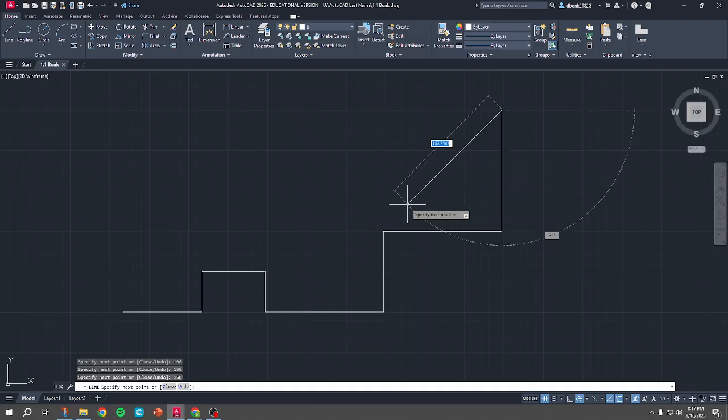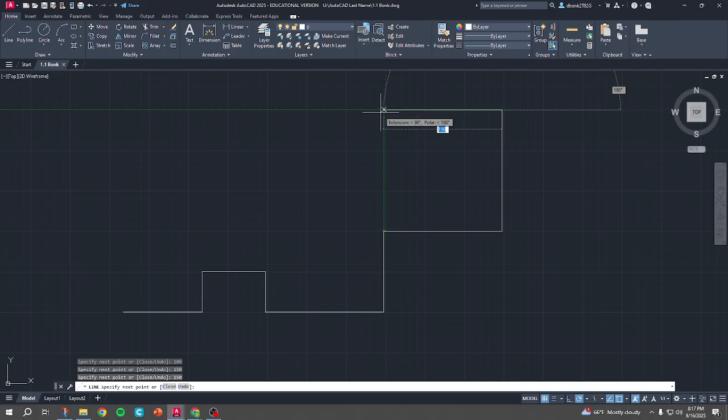One of the tracking things that you'll get is point tracking. I'm going to make this line up here the same length as the one below it, and I can find that point in space, and I can drag upwards and then just click, so I don't have to type in the 150 to do that. Then I'm going down 50. There's no measurement on your page. You have to just note this from wherever you can find the measurements. This is going over 230, up 50, over 100,